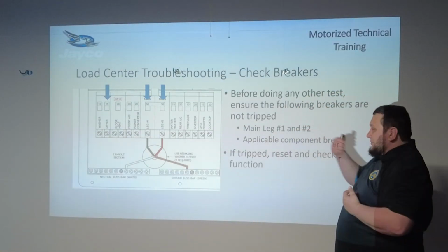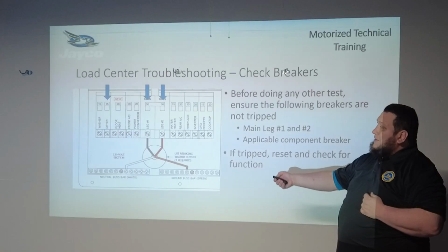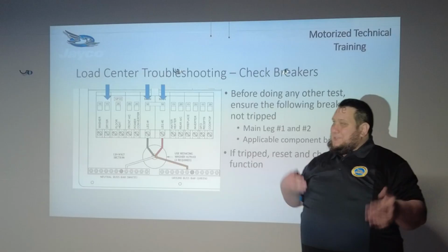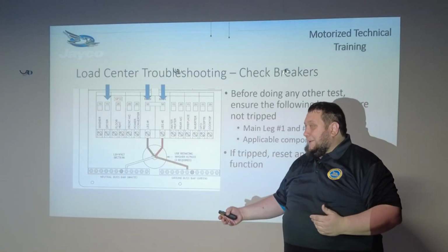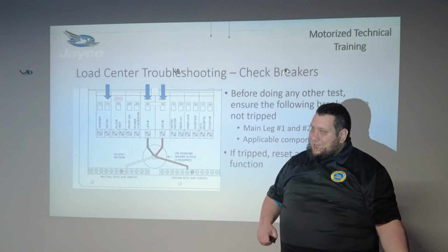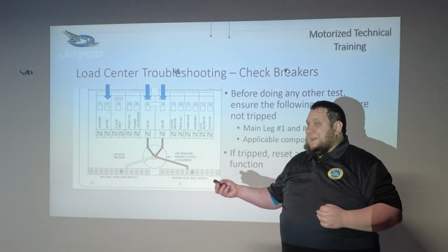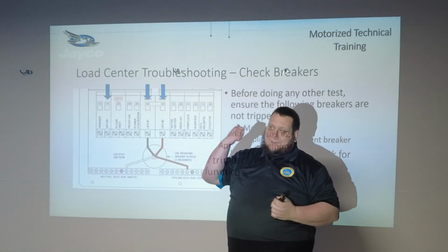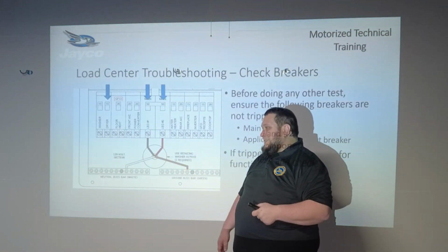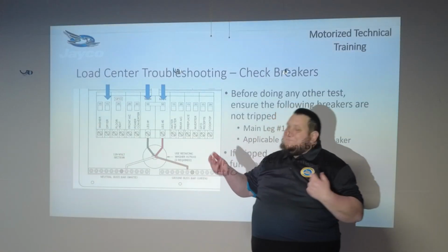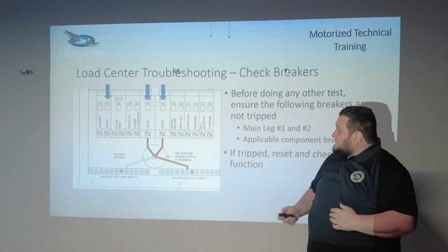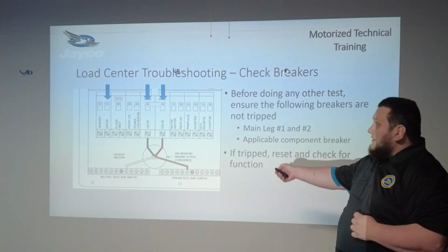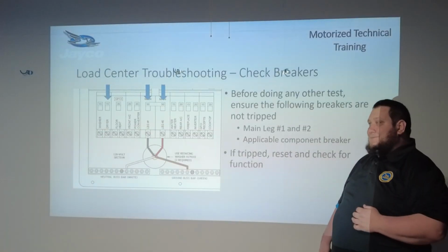Now, what that doesn't do is get at the root of why that breaker is tripped. That gets a little bit more involved than we're going to get into today, because you could be hunting down loose connections at that point. You could be just simply having put your coffee maker and your hairdryer on the same series and tripped it that way. But that is our number one first step anytime we're doing any sort of electrical troubleshooting. Reset your breakers.